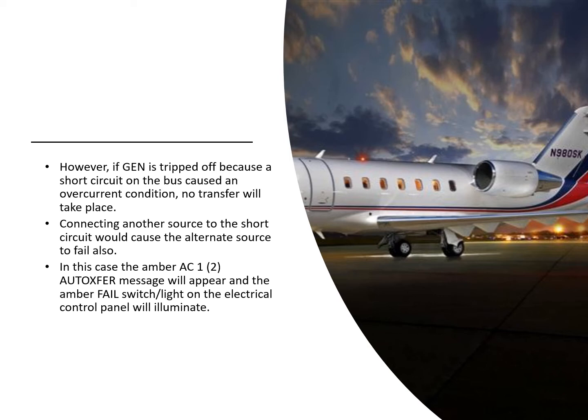So in this case, you will get an amber message. An AC1 auto transfer message will appear on the ICAS, and an amber fail light will light up in the switch on the control panel.